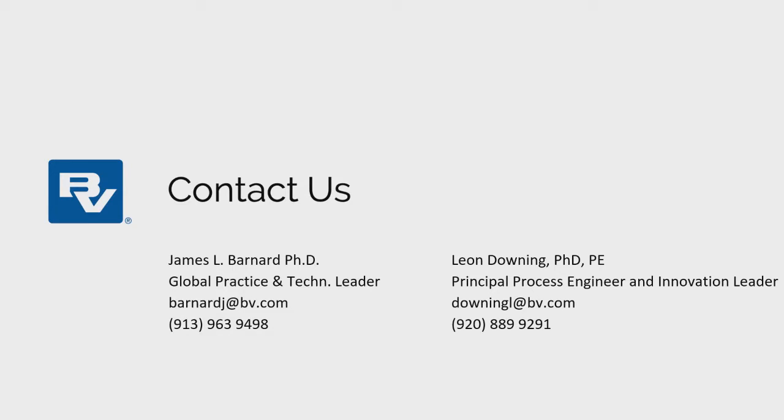The second question was, can a 1.7 milligram per liter total N and 0.16 milligram per liter total P be achieved? And if so, what technology assures compliance with these limits? So I'll take a first stab at that one. What we're presenting today makes the most use of your carbon and is the most efficient way to do biological nutrient removal. If we're capturing some of these sidestream, this RAS, the COD bound in the RAS to drive biological nutrient removal, it makes your carbon go farther, which allows you to get lower effluent limits. Now, that might not be the whole solution to 1.7 and 0.16, those are pretty low limits, but it's part of the package.